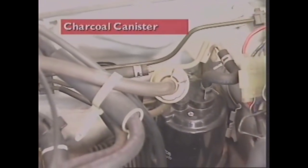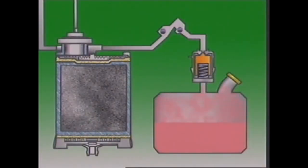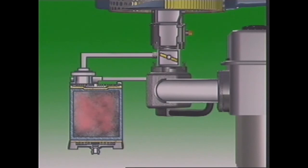The char canister is a canister of activated charcoal, and it's a temporary storage device for vapour from the tank. When the engine is stopped, vapour from the tank passes through the vent pipe to the canister and is absorbed into the charcoal. When the engine is running, the lower pressure in the inlet manifold draws the petrol vapour from the charcoal into the manifold. The process is controlled so it doesn't upset the air-fuel mixture.